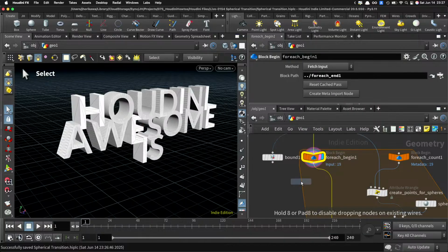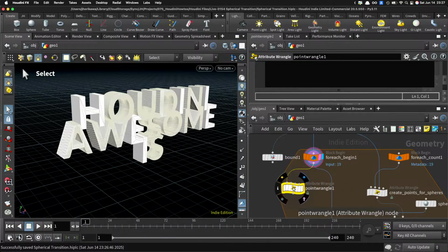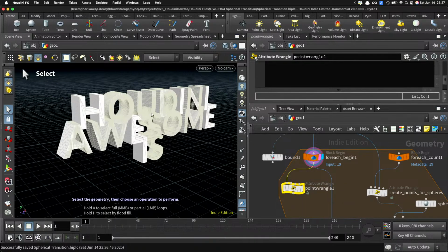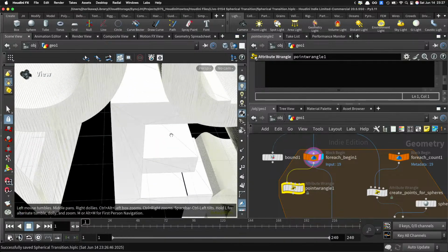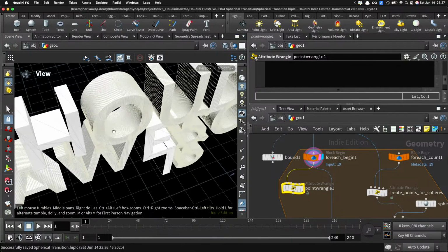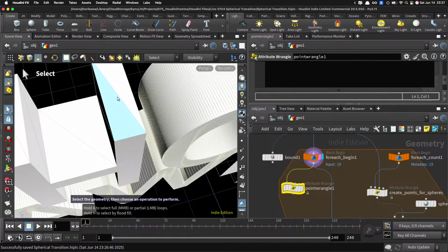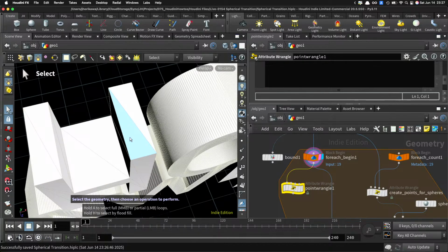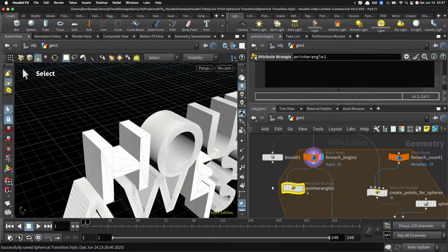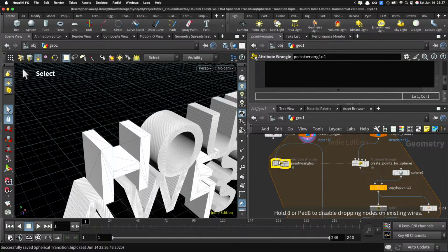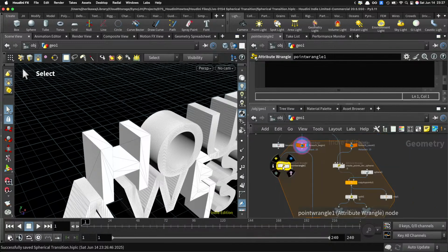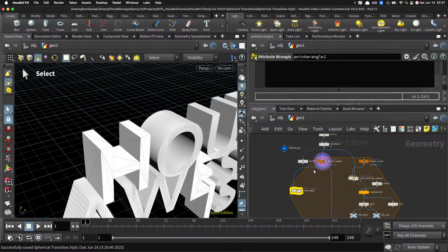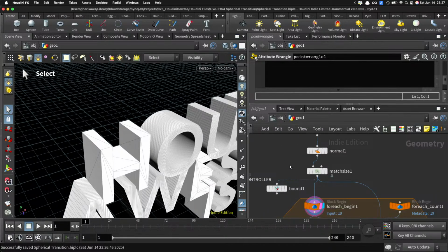create a point wrangle. Now in order to create clean slices, I think I need to have a bit more number of points, and at least it needs to be remeshed to have a bunch of points, so that we could have more, how do I say, precise interpolations between the points as a value, in order to determine where will be the sections when we use the clip. So for those purposes, let's try using remesh.